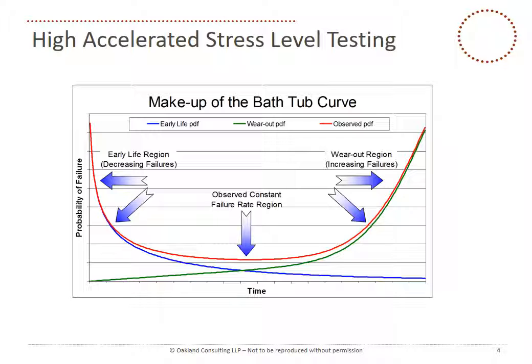The early life period is really the most difficult period to work with because there are so many potential weaknesses emanating from a process, from design, from weak components, etc. After the early life period expires, we go into the more intrinsic steady state, easier to predict. So a lot more emphasis must go on how we manage and perform our early life reliability stress testing, and how we make sure that our test is indeed strong enough to stimulate defects.